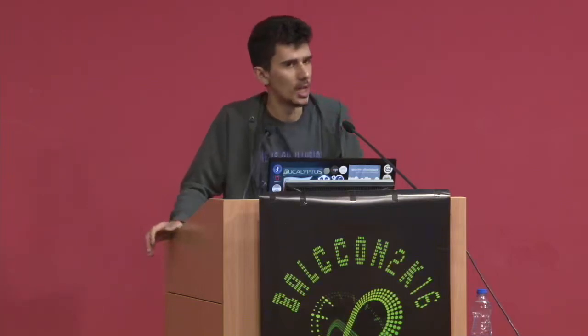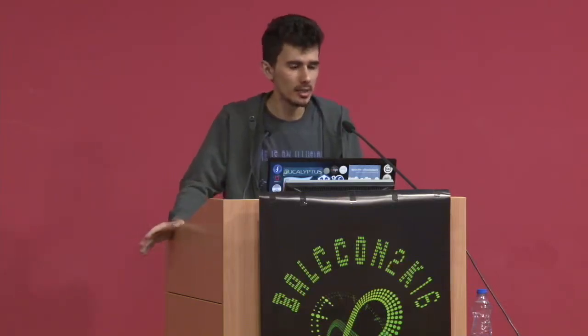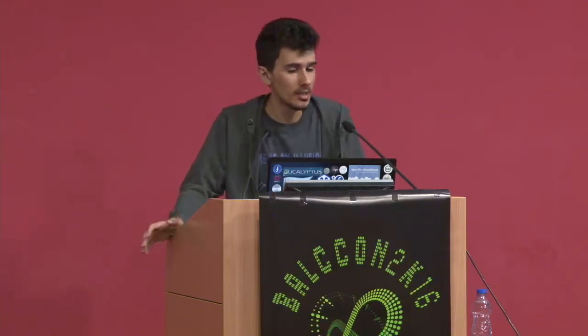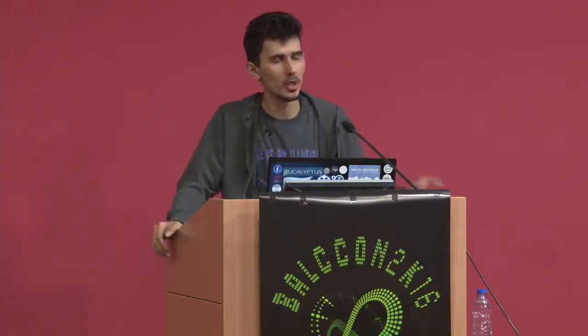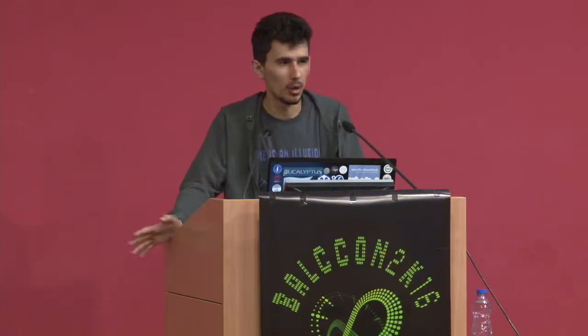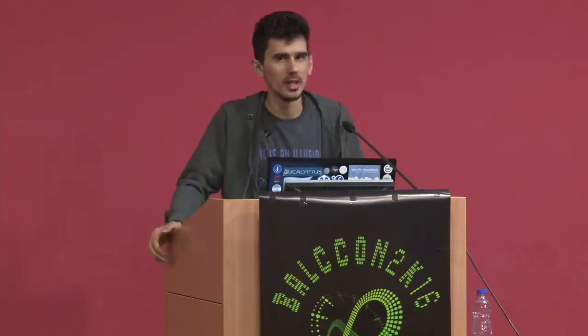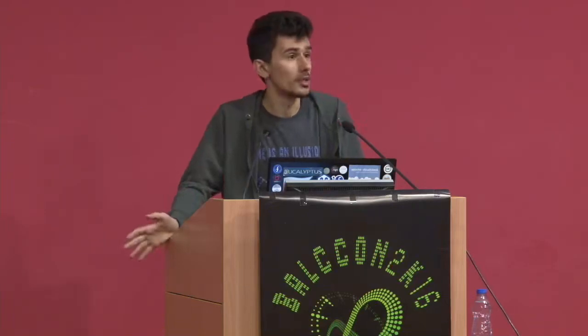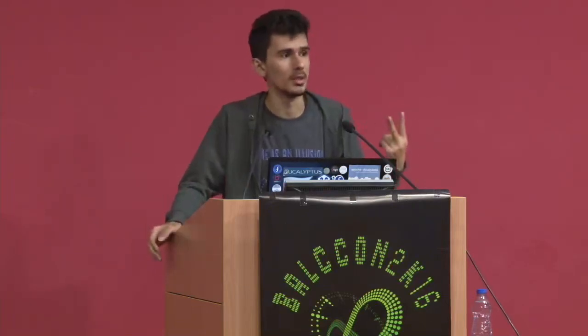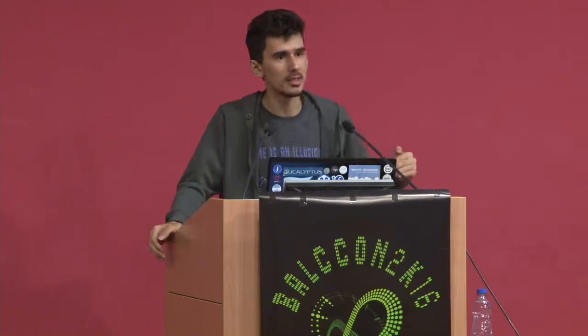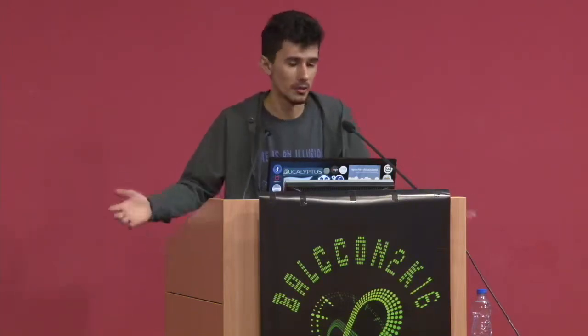But let's say you want to control motors, multiple of them. Then you're going to need something extra. For this, I'm using I2C because it's really nice. It's just two cables. If my chip supports it, which also depends on your hardware, I can connect 10,000 motors to one device with two cables. I just need to write the address list and I can control them, which is very nice.